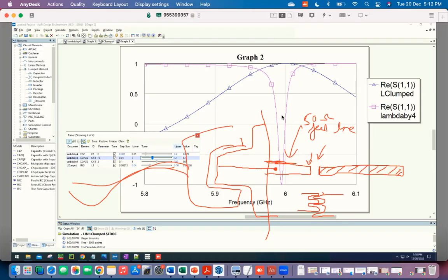So if you wanted a series capacitance, then you need a break. That's just terrible, right? I mean, you won't do that, but you can, and in fact, you can see this sometimes when you're measuring in a vector network analyzer, that while you are connecting the cable, there will be a particular time where the pins would be very close to each other and not fully connected, and you will see a resonance peak show. Because at that point, the capacitance would be just right to give you that, but it will be like a momentary thing. You can play around by loosening the nut and creating a resonator like that. That's not going to be stable.